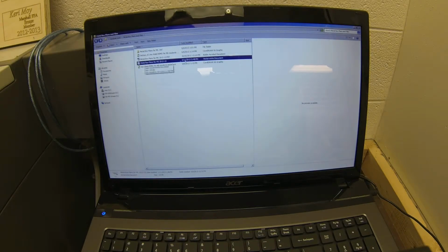As we take a look at our different files, I have tag marks on them that say what type of file they are. So you can see the one that's highlighted in blue is a Vectorworks document. That is the type of document that you would open and work on in Vectorworks. You would save it on a daily basis, and you would have to reopen it with that program. If you have exported out or saved and then emailed to yourself a Vectorworks document or .vwx, it will not work for what we need to do. Please pause the video, go back, and re-export your items out as DXF.